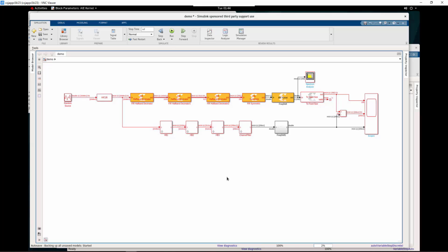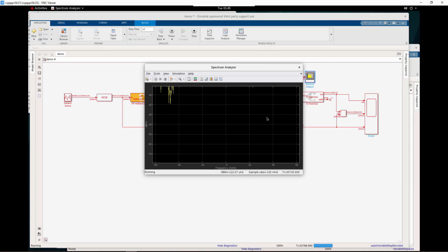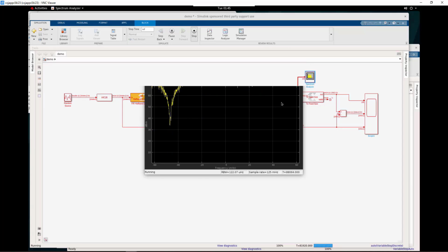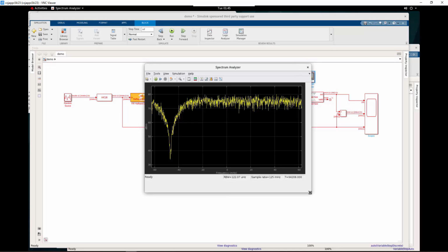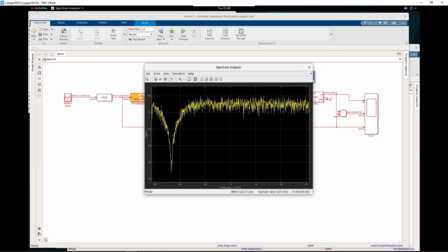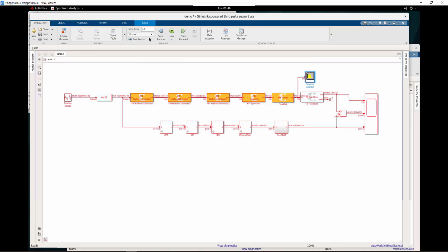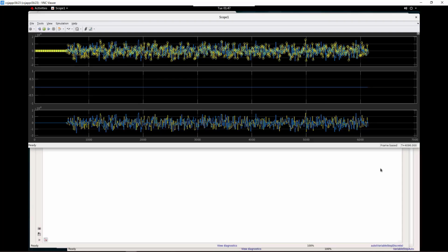Simulate the design. You can observe the frequency shift in the spectrum. Observe there is no difference between the AI Engine filter and the Simulink tool filter output.